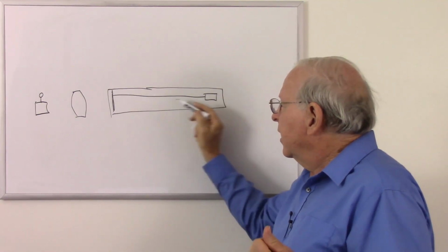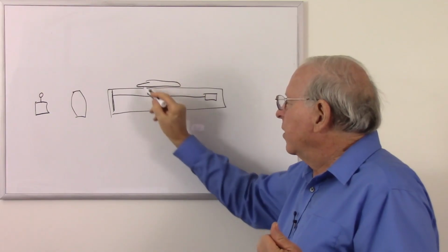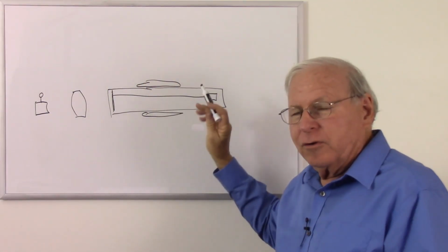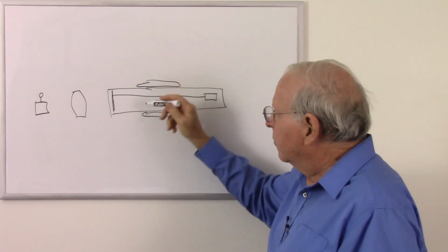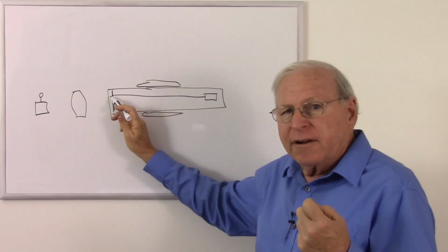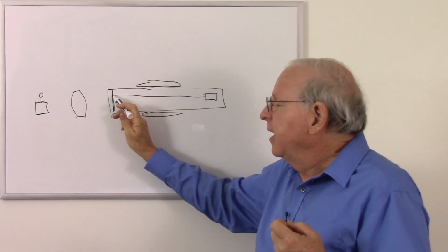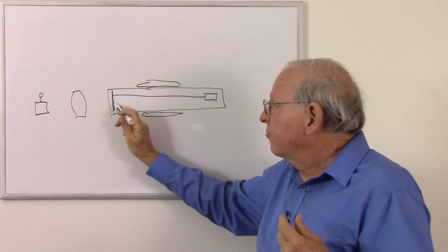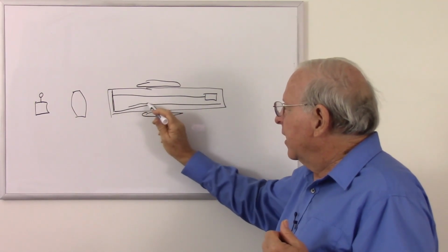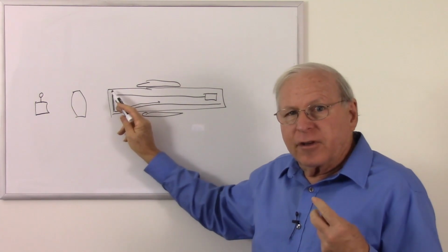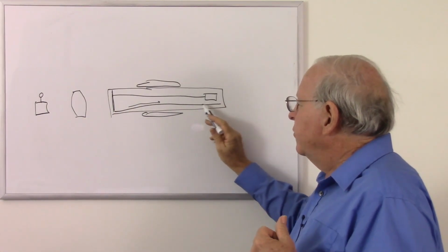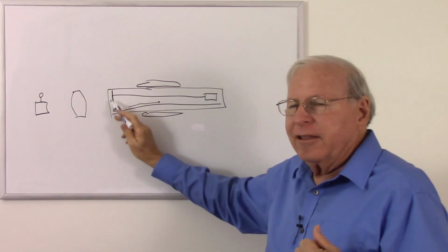As this electron beam is steered, with our coils, which really go along the whole tube to give us lots of area to work with, when it hits a spot where there's a lot of light hitting the photoconductive material, it's going to conduct a lot of those electrons away on a wire to the back of the tube, so we get a fairly high current. But if there's a darker area, we get a lower current. So we get a current going to the back of the tube that's proportional to the light hitting the screen.